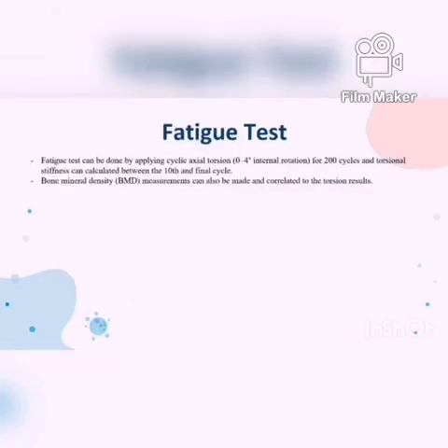The next test is the fatigue test. A fatigue test can be done by applying cyclic axial torsion for 200 cycles, and torsional stiffness can be calculated between the 10th and final cycle. Bone mineral density (BMD) measurements can also be made and correlated to the torsion results.